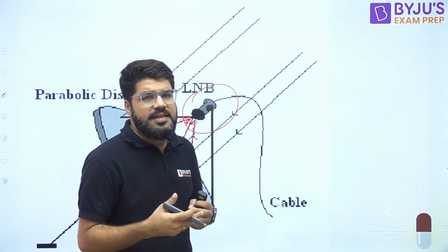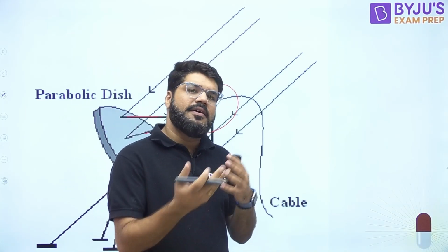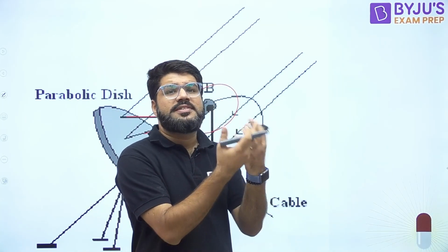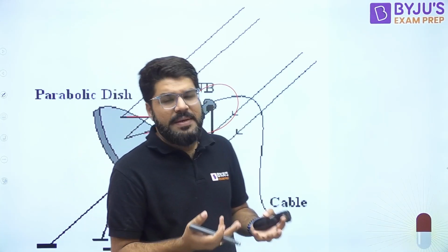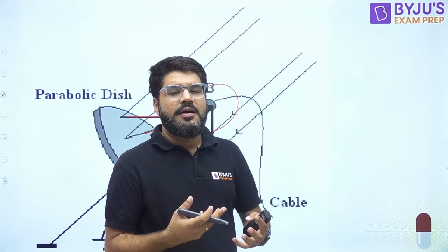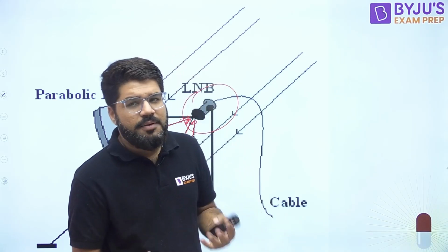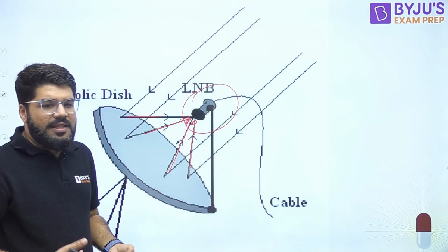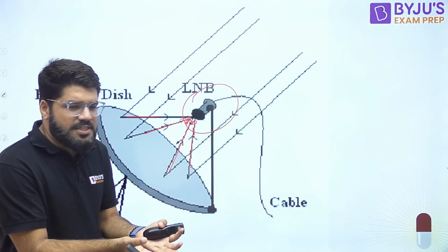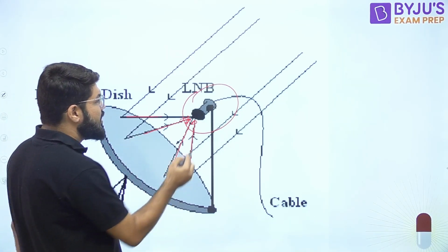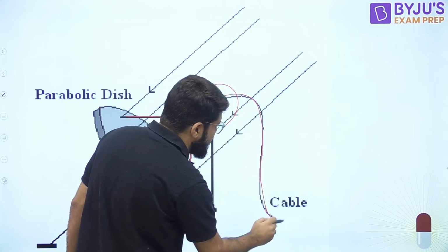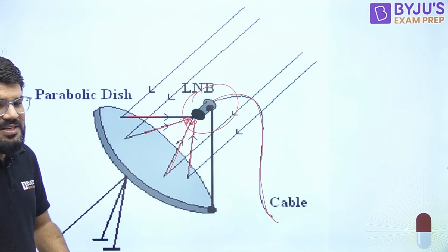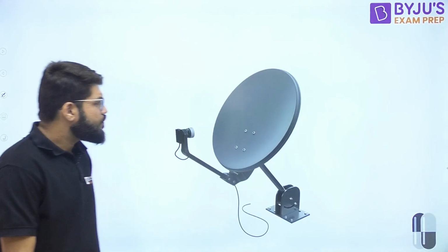The signal through the horn antenna and waveguide reaches the probe, and the probe converts the EM energy into voltage signals. The voltage signals reach the PCB, where the filtration process and all the signal processing is done, and finally that processed voltage signal is transmitted to your internal TV setup box via the coaxial cable, as shown in this picture as well, right?